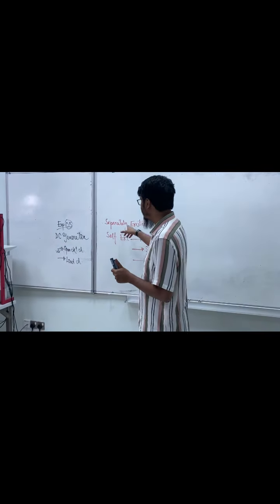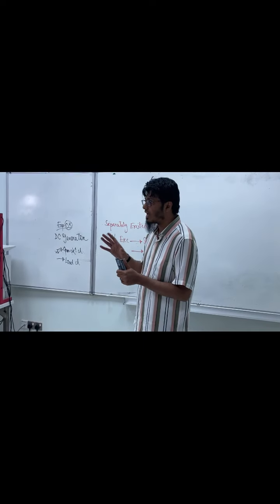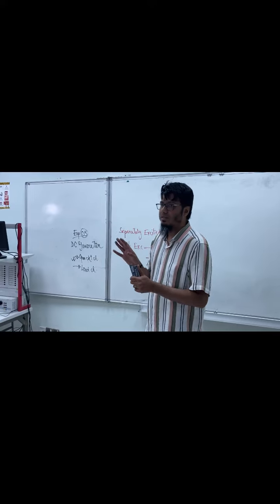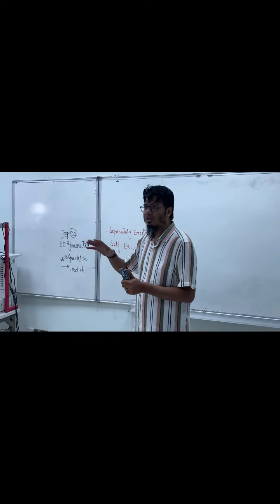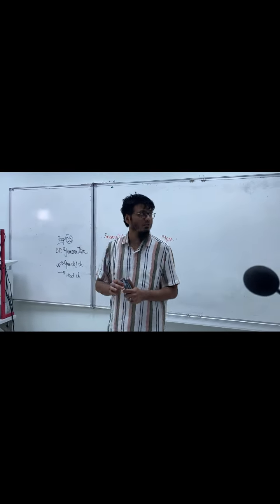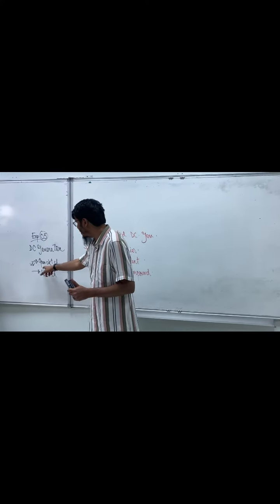Always we choose the separately excited DC generator. Why? Because in the separately excited DC generator we have control over field current, and in the open circuit characteristics curve we need to change the field current, and thus we get it. Is it clear? Okay. So this is the first step, the first target, to get the OCC curve.